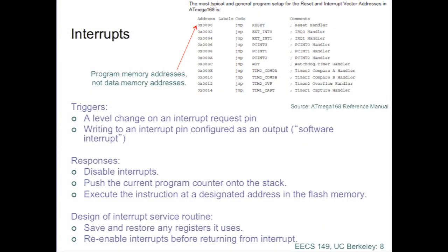Okay, let's go back to the slideshow view. Okay, so what should you do in the interrupt service routine? So when the hardware interrupt occurs, all that the hardware will do typically, and in this processor, is make a record of the current program counter, okay, and then set the program counter to this address. That's all it does, okay?